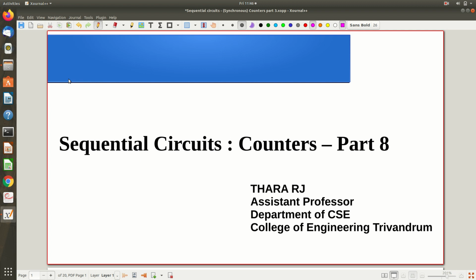So from part 1 to part 7 we discussed mainly something called the asynchronous counter. We started with what a counter is and the difference between synchronous and asynchronous counters. Then we moved on to the asynchronous counter in detail and saw many variations of it.